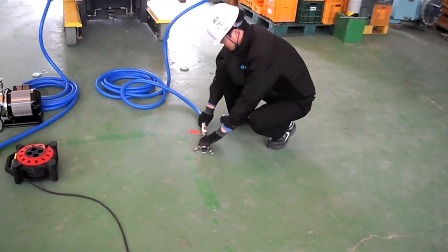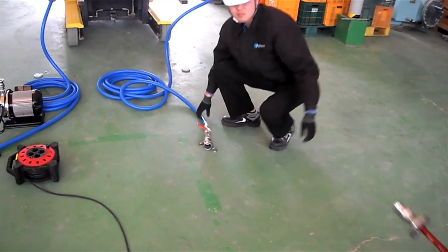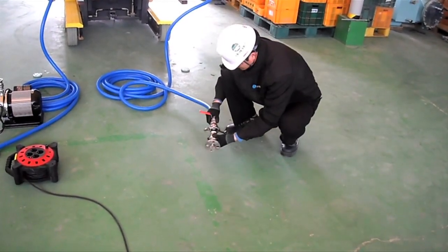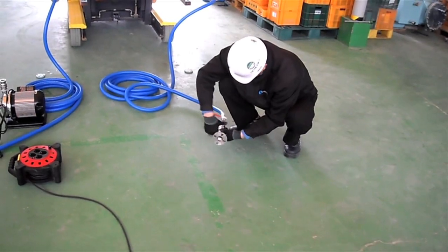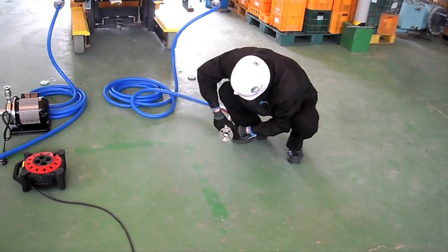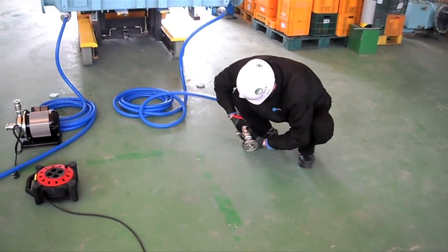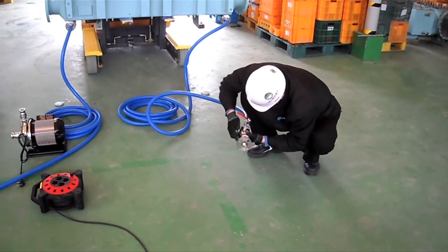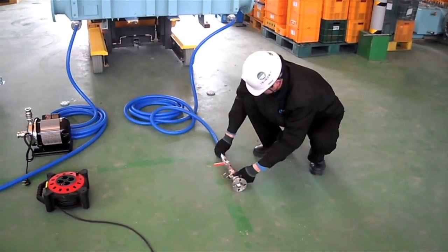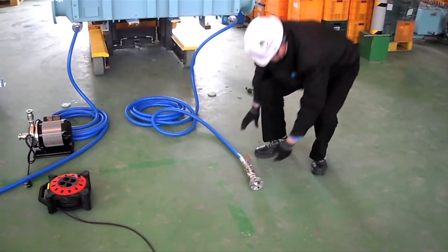6. Close valve V3 after flushing out fresh water for approximately 15 minutes. 7. Disassemble the pipe AC1 and pipe AC3. 8. Dispose of the collected cleaning agent according to the rules and regulations.